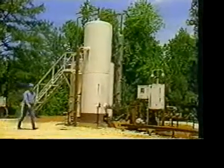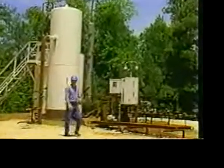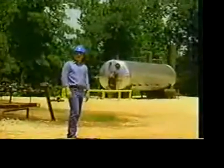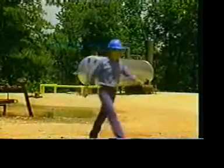Production separators are used to separate water from gas and oil. If well fluids are thoroughly mixed, they form an emulsion, and emulsions must be specially treated before the components can be separated. A heater treater, like this one, is used to help break an emulsion.